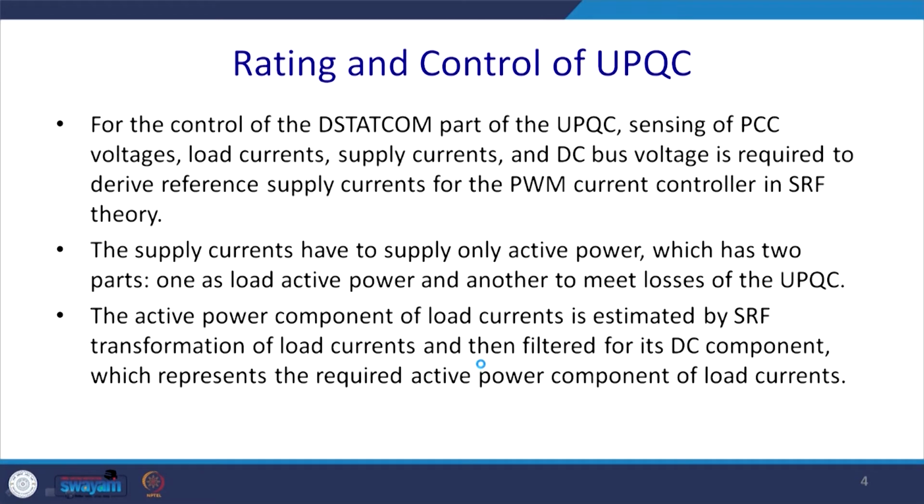So, for the control of the DStatCom part of the UPQC, the sensing of the UPQC voltage, load current, supply current and the DVR's voltage is required, to derive the reference current of the PWM control by SRF or instantaneous reactive power theory or another technique which has already been mentioned.